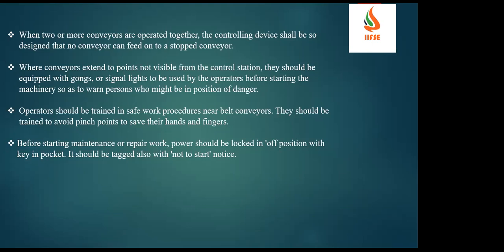So there the eyesight will not reach the people. So what will happen, they will keep a flashing beacon or an indicator, and once they start the conveyor there is an alert sound, so that anybody passing by stays alert that the conveyor is going to start. In that way we can avoid accidents.